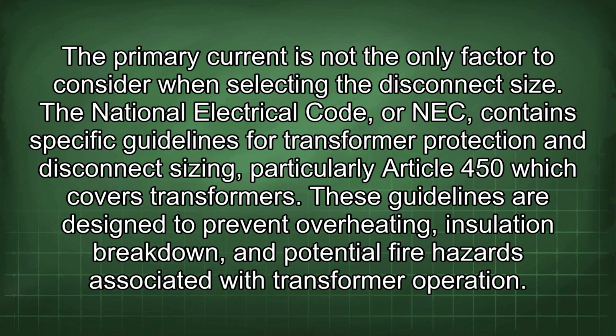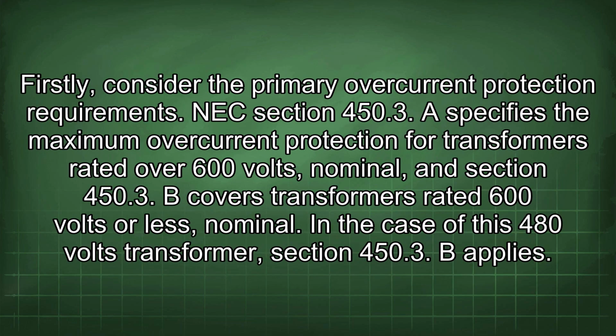The National Electrical Code, or NEC, contains specific guidelines for transformer protection and disconnect sizing, particularly Article 450, which covers transformers. These guidelines are designed to prevent overheating, insulation breakdown, and potential fire hazards associated with transformer operation. Firstly, consider the primary overcurrent protection requirements.